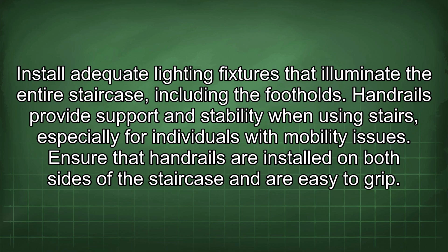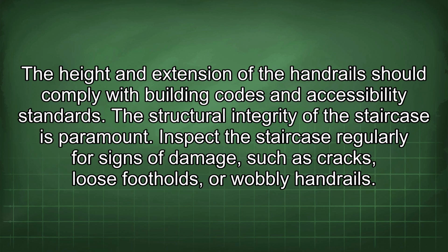Handrails provide support and stability when using stairs, especially for individuals with mobility issues. Ensure that handrails are installed on both sides of the staircase and are easy to grip. The height and extension of the handrail should comply with building codes and accessibility standards.